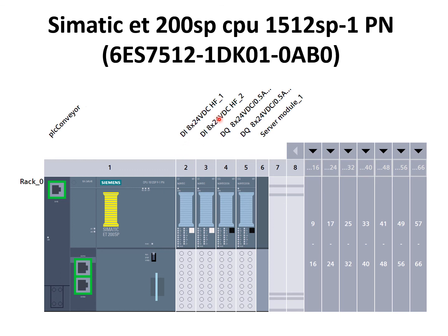Digital input module with 8 inputs and 24-volt DC. And for the output, digital output, okay, so in PLCs we use Q instead of O to avoid confusion with 0, so that this means digital output, and this output module could accept 8 digital output ports, and it has 24-volt DC.